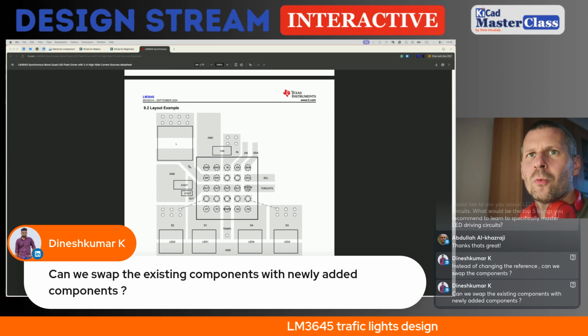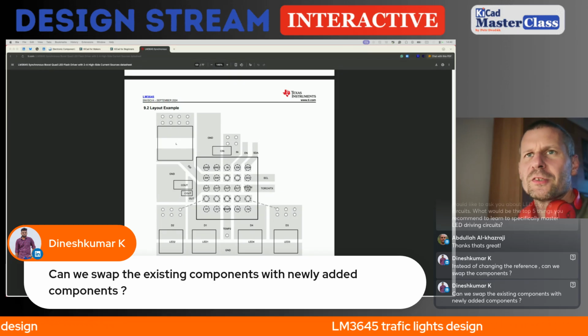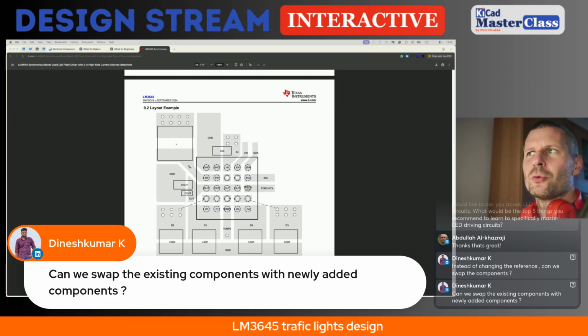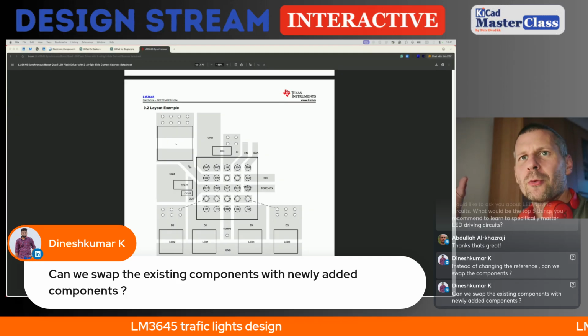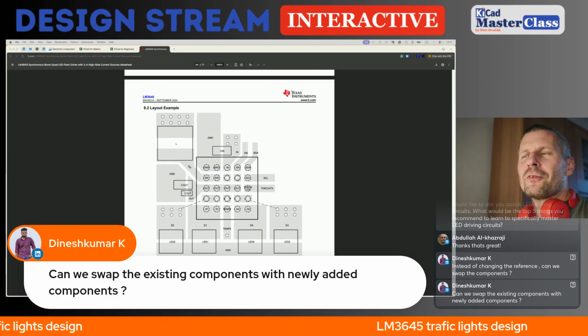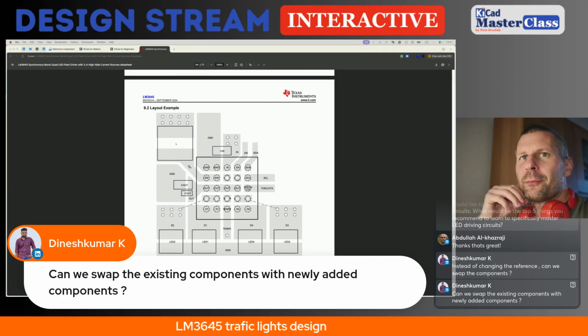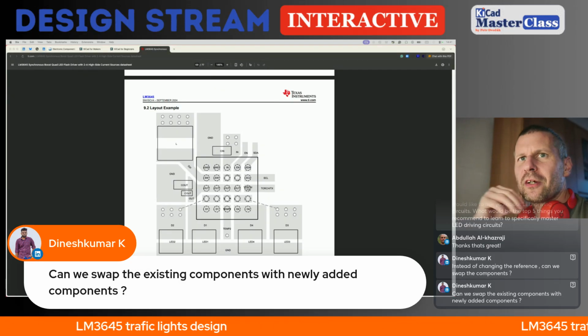There is one more comment. Can we swap the existing components with newly added components? Yeah, sure. You can swap them, but I didn't want to move them from their positions because I spent a significant amount of time placing them. So instead of pushing them around on the PCB, I changed the reference designator.